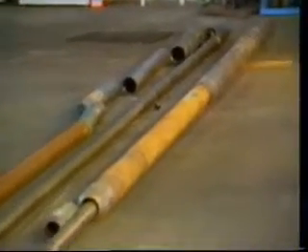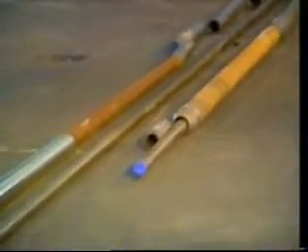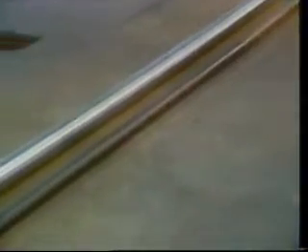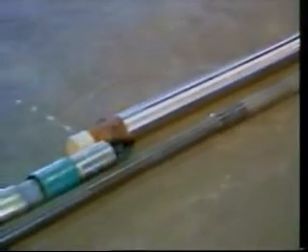A work string should be used in order to prevent wear on the often lighter production tubing. The work string should be cleaned thoroughly before use. Conventional cased hole single zone gravel pack operations use tool assemblies like this one, which is run on the work string. The particular tool shown here enables acidizing and high density gravel packing in one trip.